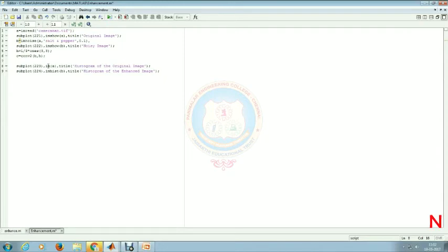So in the third window, let us display this smoothing filter output. So imshow of C. Here we'll have to convert this to unsigned integer format, so uint8 of C. Let me give the title here: smoothing filter output.